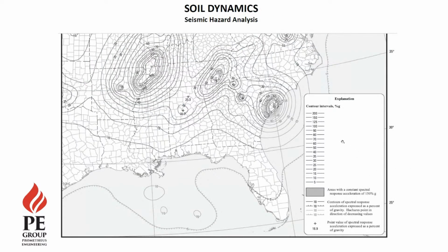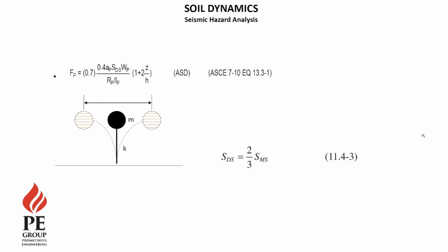Then we talked about building a particular structure somewhere. And how do we know the kind of vibration it's going to experience based on earthquakes? So we took a detour into some basics of soil dynamics, and there's something called the spectral acceleration. It's a very important aspect of coming up with the acceleration that your structure is going to feel. And that is based on the response, a displacement response, velocity response, or an acceleration response, all these space-time responses of a single degree of freedom structure with a particular period to a particular input motion. Okay? Input ground motion right here.